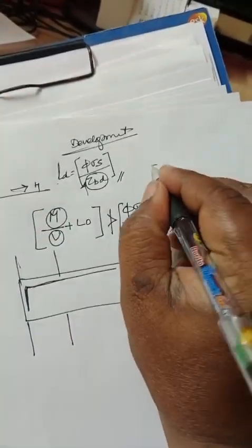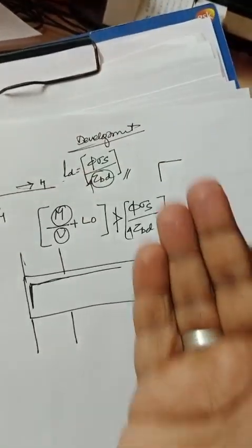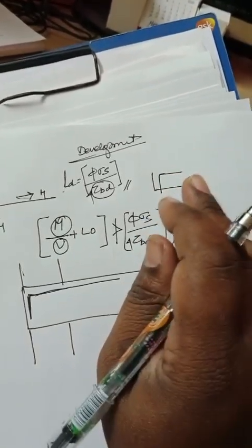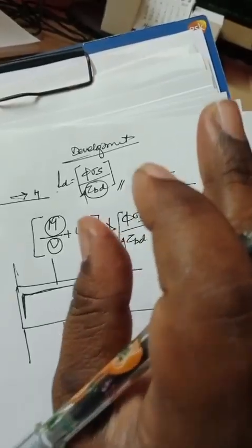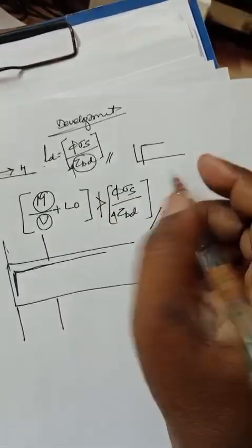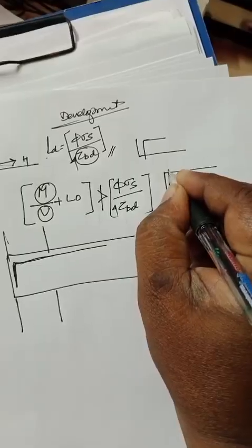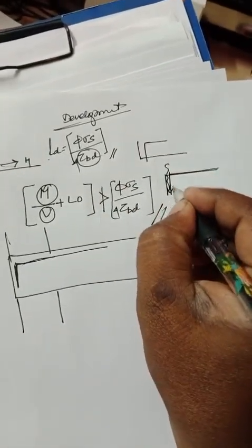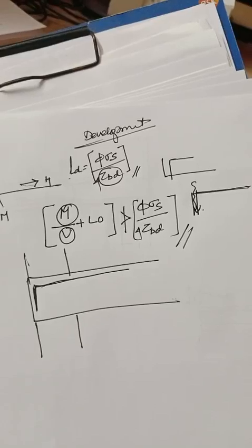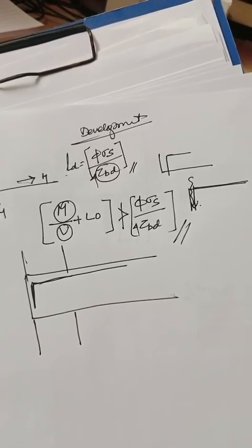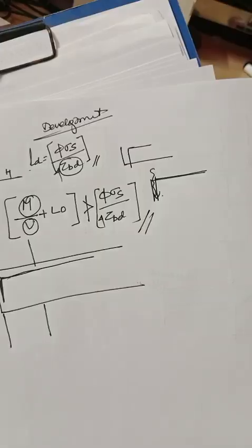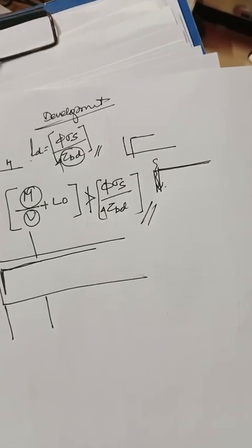Based on the plane, you are providing the reinforcement pattern, bending downward or bending upward. So this is how we have to decide. So it is better to avoid upward bending. If possible, provide downward bending only, and make alternative bars with a slight 1 inch gap. Just provide one more bar here, alternative bars like this, so that concrete can go inside. I do not really understand how, if you are bending upward, the congestion will be avoided. Anyway, we bend downward and make some slight changes here. Just 1 inch, you shift this reinforcement so that the space will be created. I am talking about alternative bars. So you do that, and the problem will be solved.